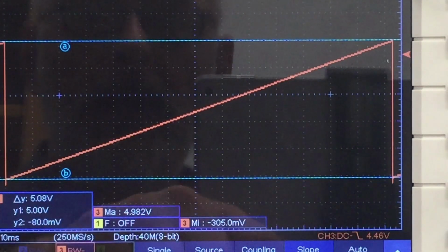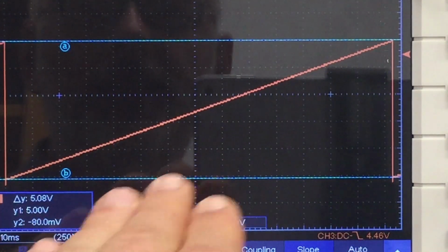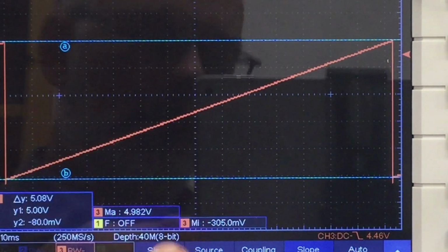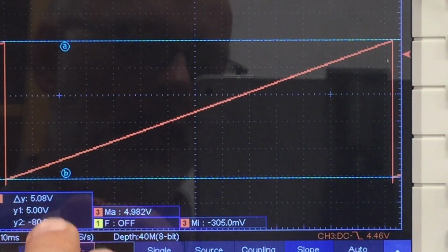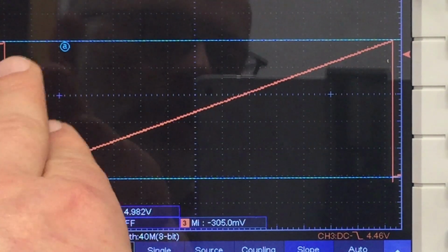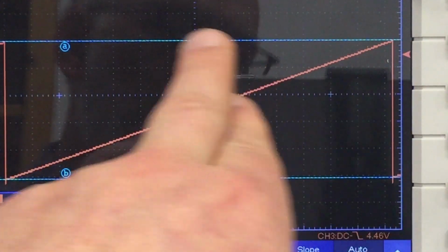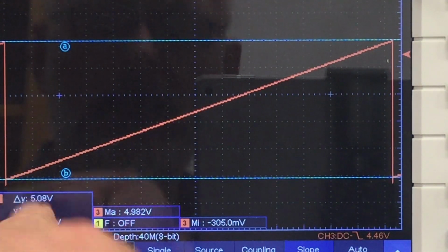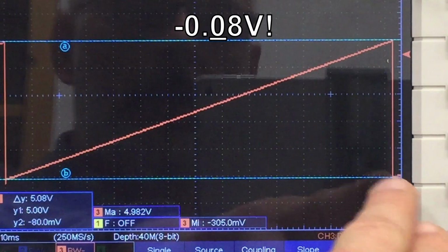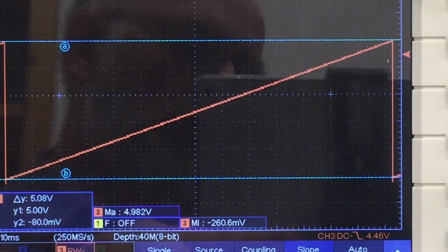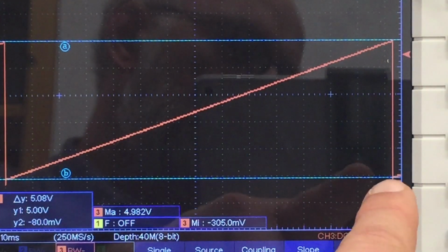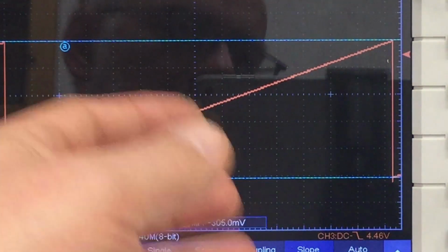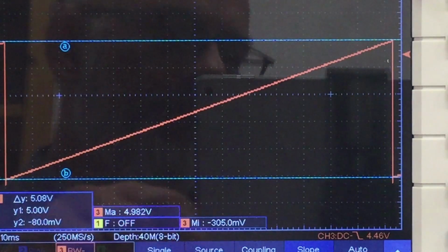screen. And I fine-tuned the voltage levels on the oscilloscope. So we have 5 volts here at the top cursor line, and we have 0.8 volts at the lower cursor line. And you see, it's making little peaks here. That's, well, it's a cheap function generator.